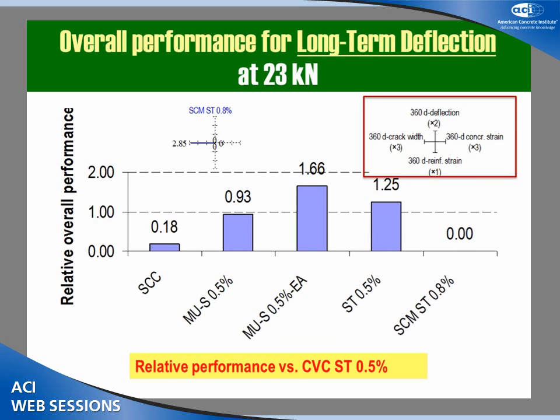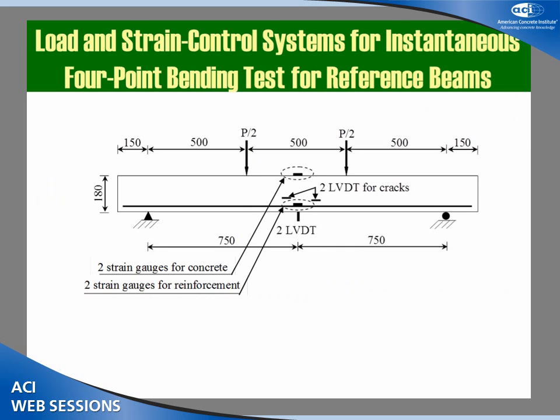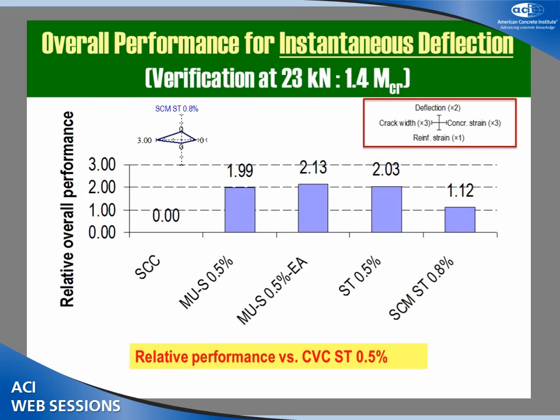So here we are comparing the structural performance of beams under long-term deformation. Among others, we're looking at the crack widths, and we start to compare different types of fibers, and I'll show the results in the conclusion. And then we had a third beam, so there were always two beams, but a third beam after a year and a half, we tested it in flexure, and we look also at the different structural response. So we can compare the instantaneous deflection characteristics versus the long-term deflection.